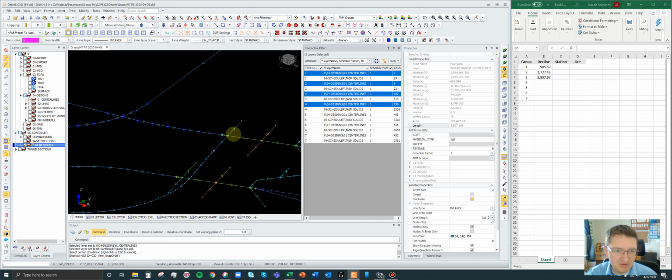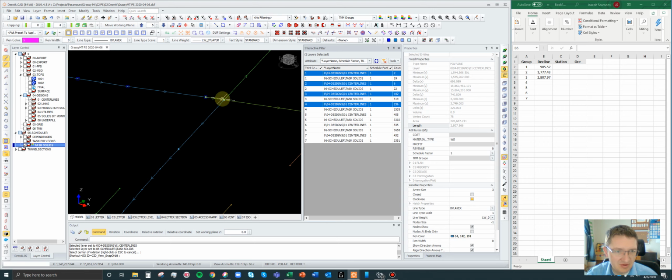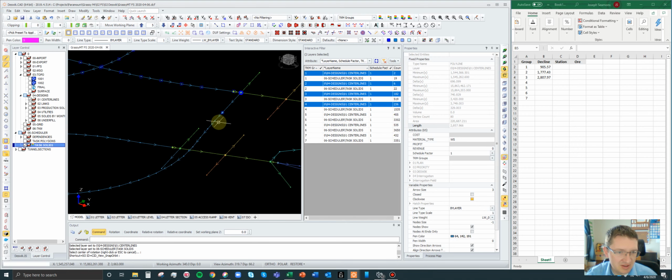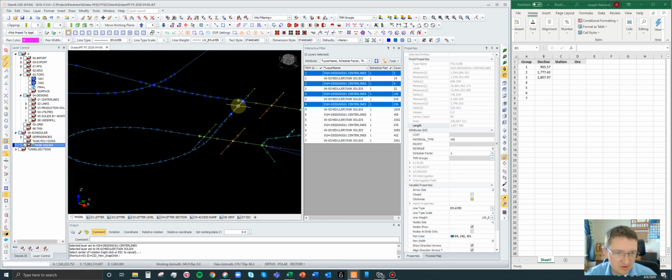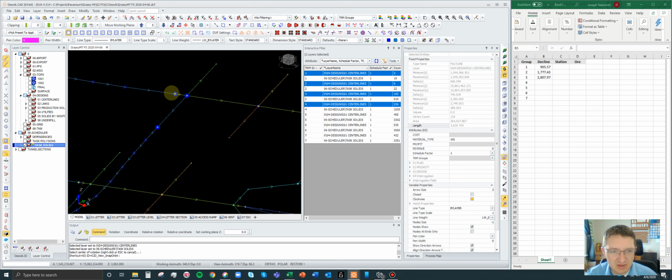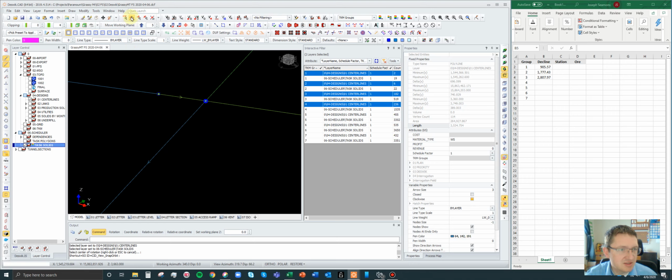Now this one, you have to see that there's a little bit right here and then it comes out. What is that distance right there? And the other thing is, these are 2 different lines right here. See? There's this little 50 feet right there. And then there's that. What is this distance? So to measure a distance just manually, because if I click this, it's going to measure the whole thing over there. I don't want that. But let's just get the distance. So you can come up here and do tools, query distance.